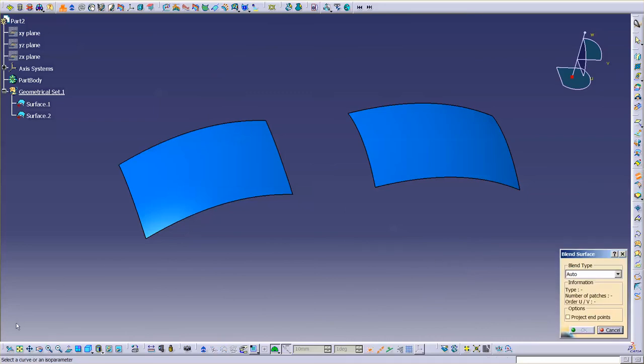And if we look at our Q line, it is asking us to select a curve or an isoparameter. So for this, I'm going to select this edge. You'll notice that I get a little red indicator, or pre-selection, of what edge I want to pick. I need to be careful to not pick something over here or one of the other edges. You just want to pick near the edge that you want to bridge across or blend across.